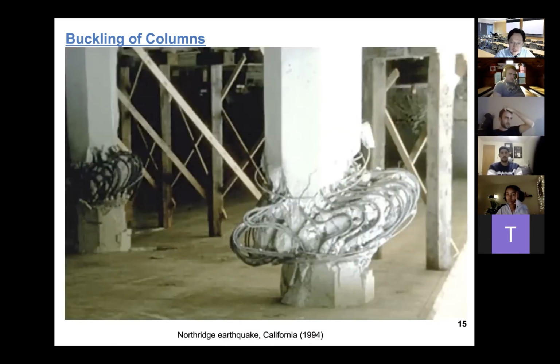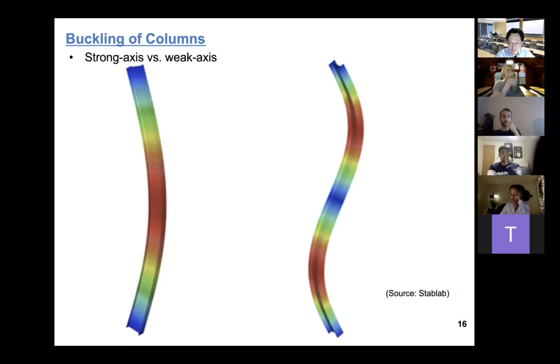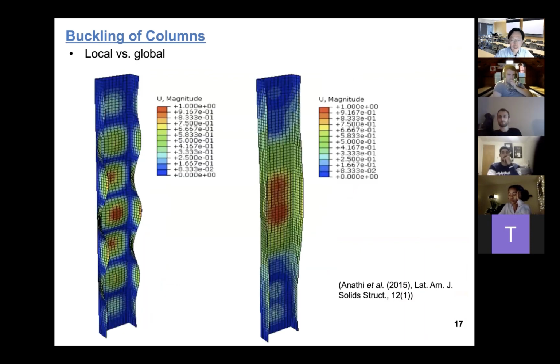And certainly, global buckling theory cannot predict the deformation of details, like in this case, detail components such as reinforcement. Numerical simulations can give you some ideas about how we can predict the buckling, but it will not tell you what the buckling load is. This has to be separately calculated. But what the numerical simulation can do is tell you where the buckling is likely to occur.